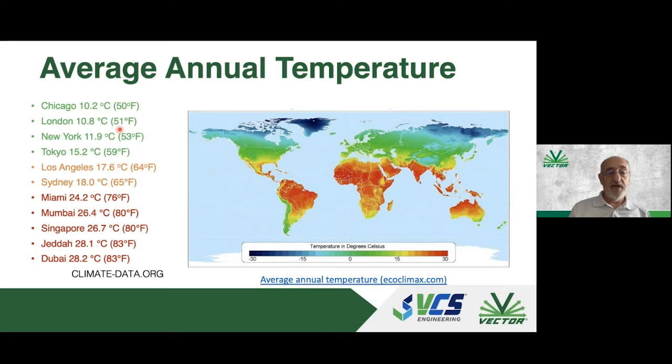So what we have done is taken an average for all our readings in the UK, for example. The average for the year is 10 degrees. So we're basing current output and exact current output on 10 degrees temperature. And if you have 20 degrees, then you know that your current output will be double. But as I said, the corrosion rate would also be double. But up to about 15 degrees, it works out that the XP anode that we have designed is ideal. It has enough surface area for the current output to be the right amount.